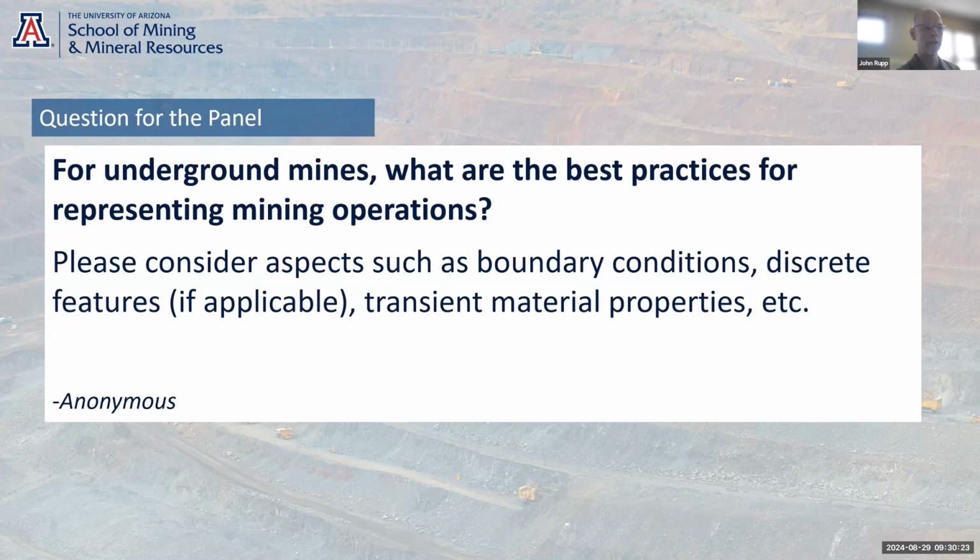If you have a drift going through a large mass of crystalline bedrock that's really tight, then probably a discrete feature is going to be the way to go. You would need to use really small model cells to capture it with equivalent storage. But if you've got a block cave or some larger stopes that scale well to the grid size, then you can use an equivalent storage, like a high storage zone.